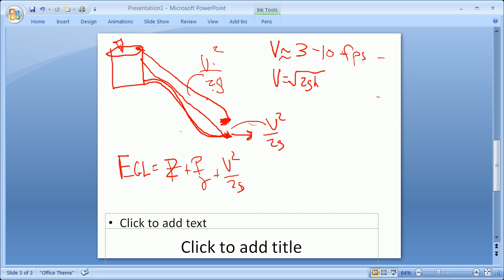So generally the steps, if you're doing a free water surface or a free flowing problem, and you know the velocity, and usually you know the velocity because you know Q and you know the area of the pipe, that gets you the velocity. Here are the steps. You calculate the velocity head, you draft where that is. You draft this to scale, probably 1 to 4.